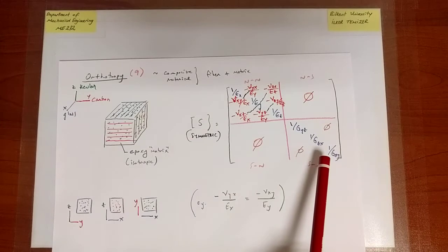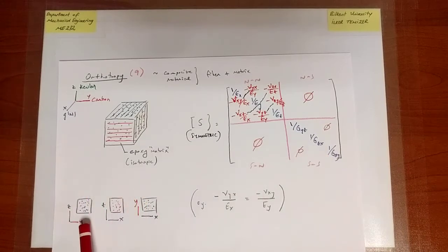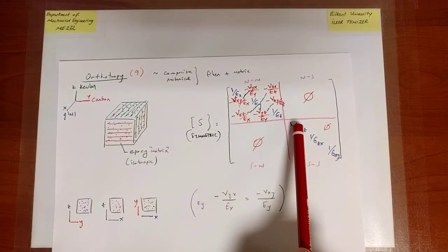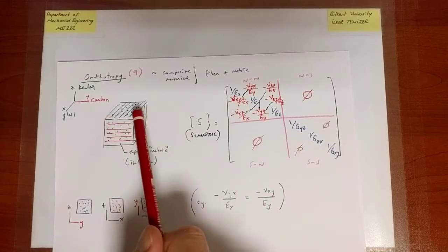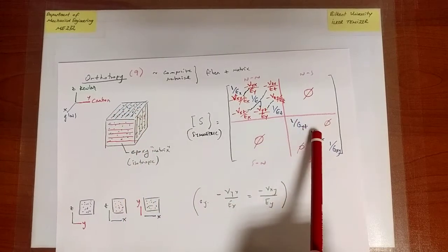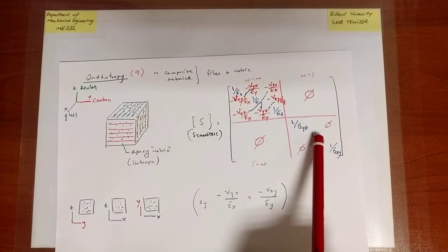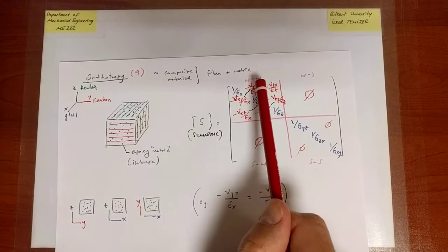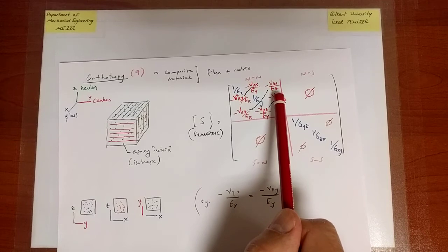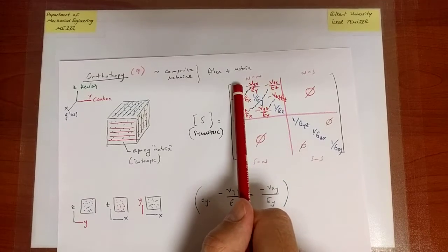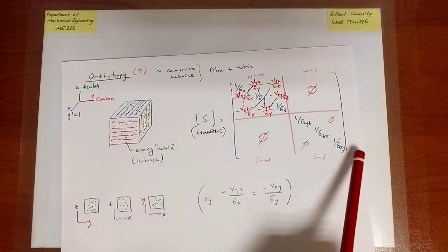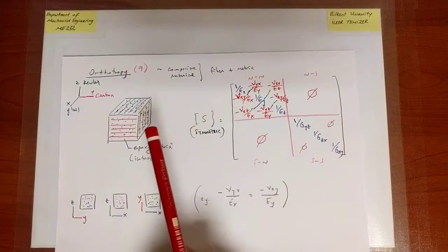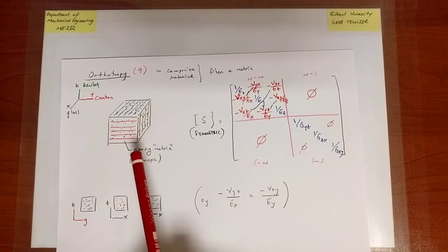So when you look at the structure and these pictures, and remember the discussion, you can deduce that the shear moduli are all going to be different in general, but in this particular case, when the fibers are the same and carbon, they're just going to be the same. One shear modulus associated with every plane. One Poisson ratio associated with all, and 1 Young's modulus associated with all. So there's going to be only 1 over E's, 1 over G's, and minus nu over E's. Does that mean that this material is then isotropic?